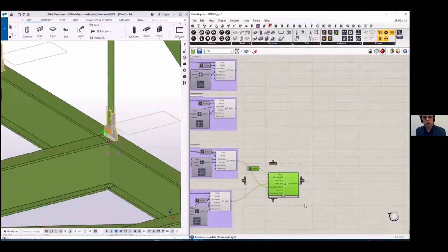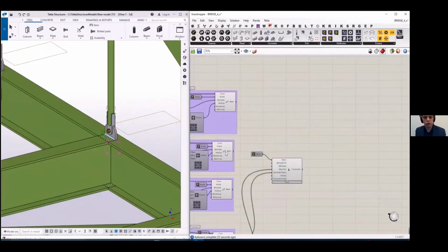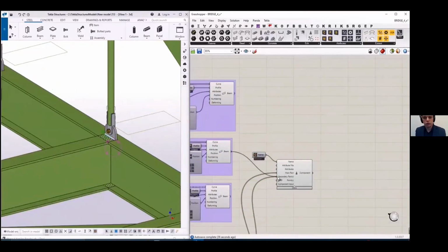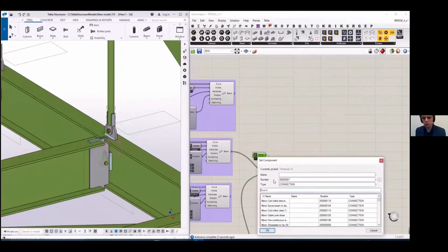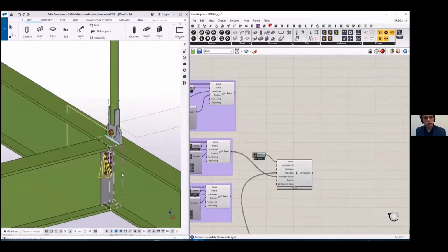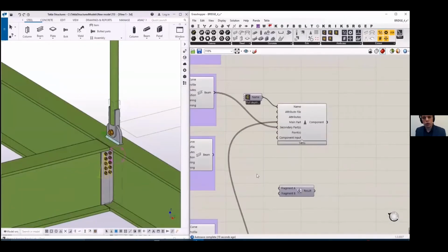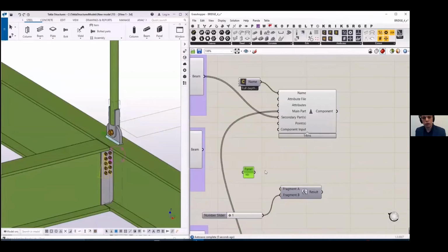And then I'm going on and copy this whole component, just change the input members, the main elements and the second elements, and we have the components there. You can also control the parameters of components. If you know the name of a specific parameter, you can find it in the attributes folder, in the Tekla model folder. So I set the name for the specific attribute.